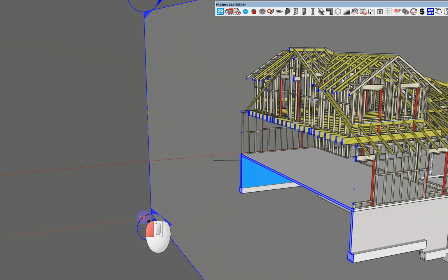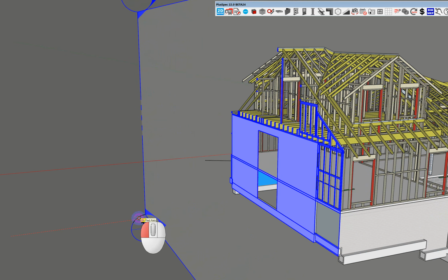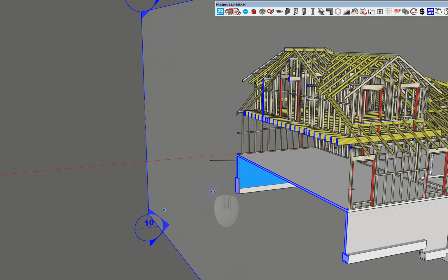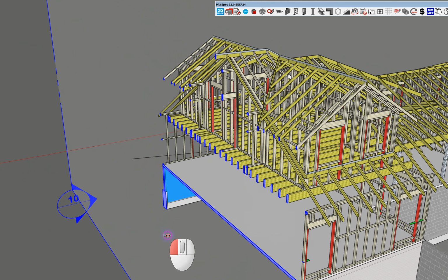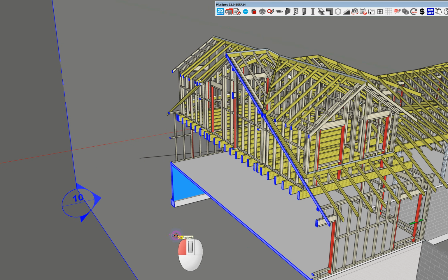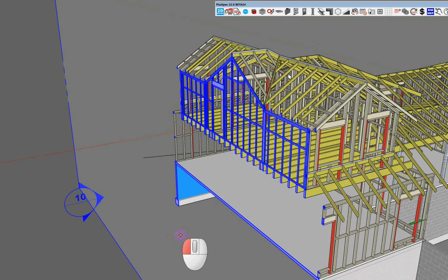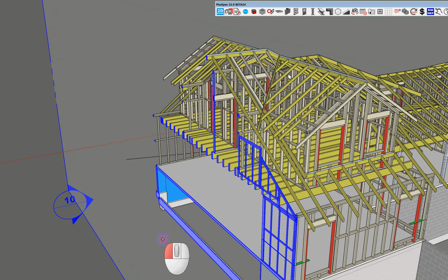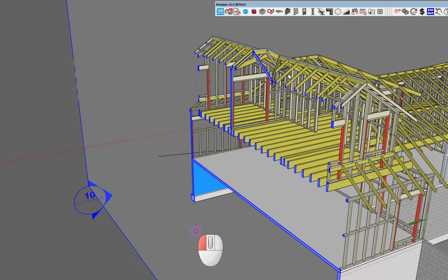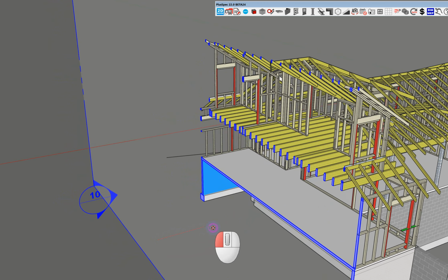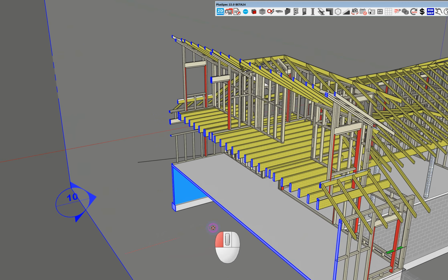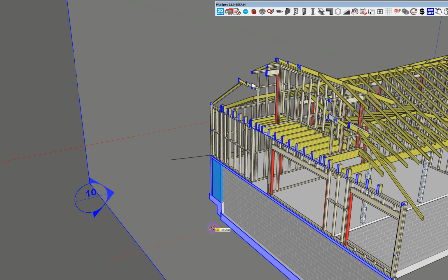Okay, so as you can see there, we have a brick wall there, and a frame wall, and a beam. All of your joists are load bearing to hold that upstairs roof load from here. So that rafter goes all the way through, as you can see. And then as we get in there, we also have wall load sitting over top as well. There's a fair bit going on here, and I'm not an engineer. I did run some calcs on those joists that appear to do the trick, but it is important to check it.